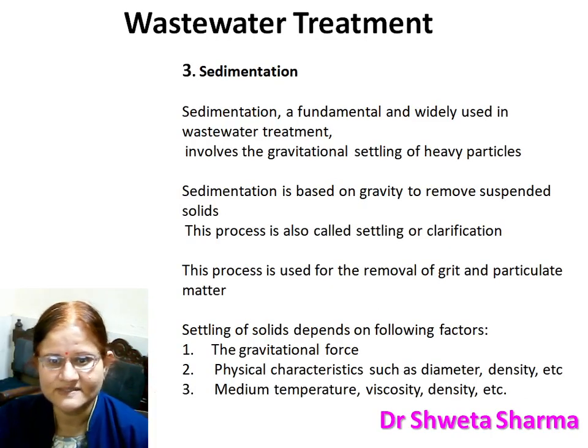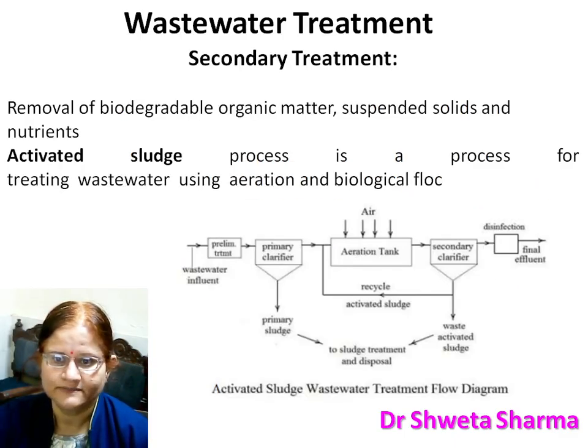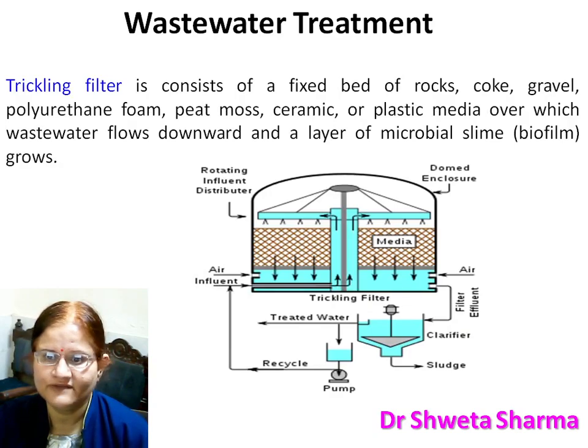The third step is sedimentation, which includes the gravitational force as well as the medium. So on the basis of gravitational force, we remove suspended solids from the wastewater. In the secondary treatment, we apply the activated sludge process and trickling filters.